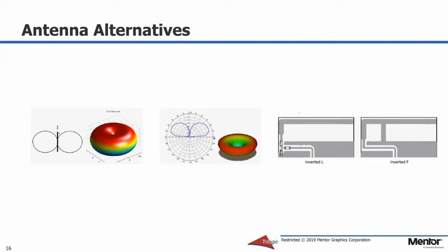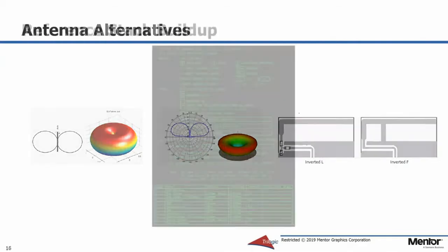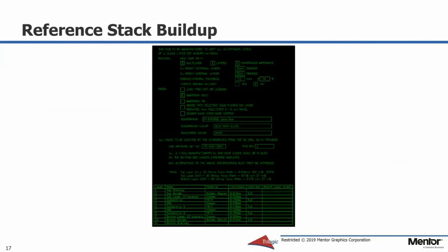It is best to start with the antenna and work your way backwards to the IoT radio component placement and routing. Again, antenna, radio, and then the rest of the design is normally a good way to prioritize the pre-design and constraint criteria. A recommended stack build-up will normally be provided and should be followed with few exceptions.